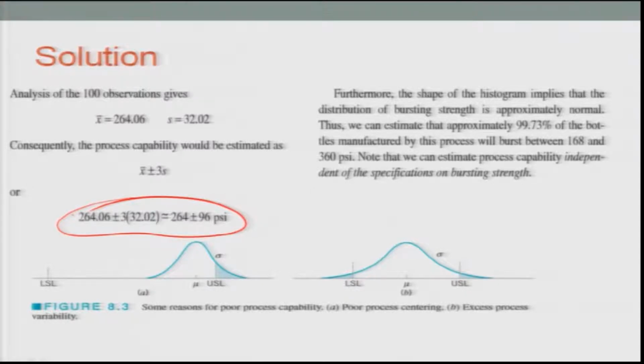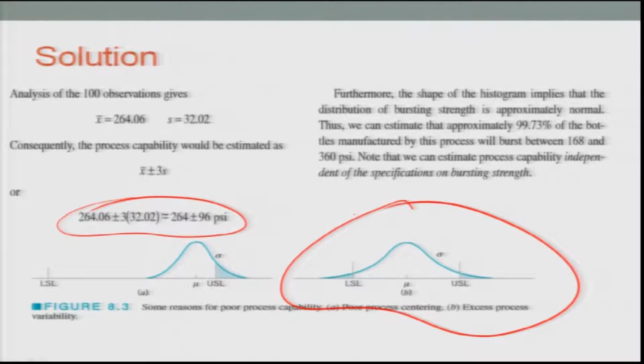So in this second diagram which you see, the central line is given as mu, and the dispersion on to the right is given by the UCL, which is the upper control limit. Then you have the lower control limit, and depending on how the process has been done, we can find out the UCL and the LCL.